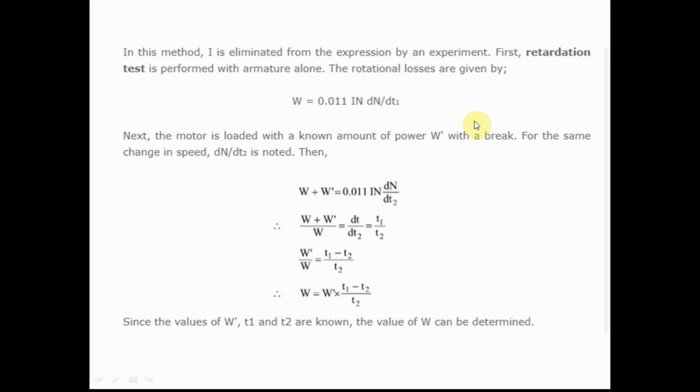Since you have included the electric load, the time taken for the motor to slow down to zero speed will be much less compared to the first case, because this pure resistive load will act as a brake, due to which the time taken to reach zero speed will be much less compared to the first scenario.